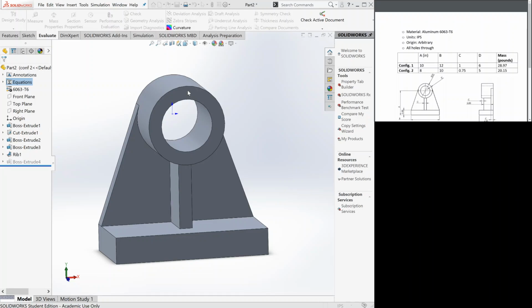So you're going to click on the little downwards arrow that's right next to it. Not on the one where it's going up and down. There's a tiny little arrow right next to this black figure with three blue dots. Click on it. A menu should appear that says this configuration, all configurations, specific configurations, and link to parent. You're going to want to click on this configuration. That means that now whatever you change will only affect this configuration. So you're going to do that same thing for all of them.